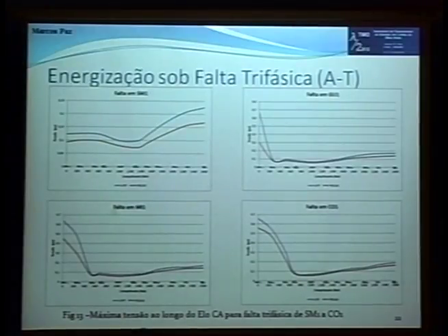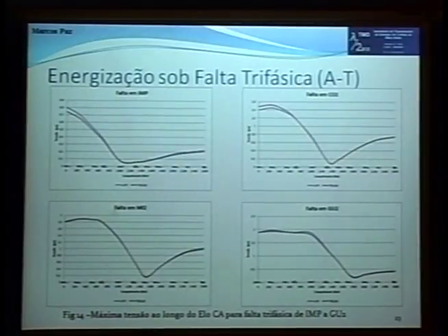So as the point of fault moves in the line for the three-phase fault, the voltages backward to the fault point become higher. So Gurupi, Miracema 1, the voltages start to become higher upstream up until the faults in Colinas 1. We still do not have overvoltages in the beginning at Serra da Mesa.